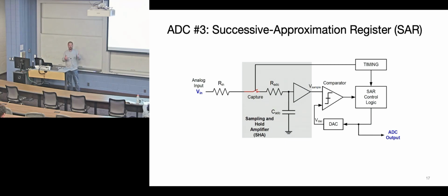We talked about flash ADC. So that was the one where it's a resistor chain, ladder of resistor values, and then so it generates voltages, reference voltages, and you're just comparing. Is my voltage higher or lower than this reference voltage? And you just need a resistor for basically every step you make.